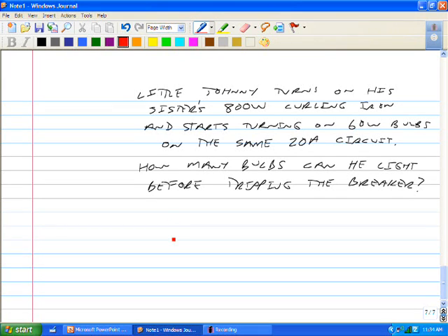So again, we can do one of two approaches. We can find out the maximum power and compare, or we can find the current and compare. Which do you want to do? Do the current this time? All right. So what current does the 800 watt curling iron use?